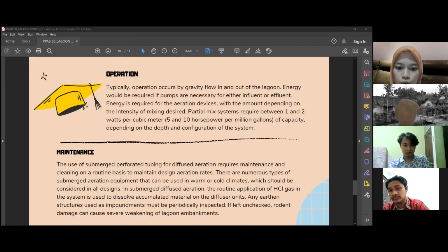Wastewater is flowed into the lagoon or pond and discharged at the bottom of the pond or lagoon. Solids in water treatment will settle near the surface or inlet, and biological particles and colloids will accumulate to form clouds or a thin sludge bed at the bottom of the pond.